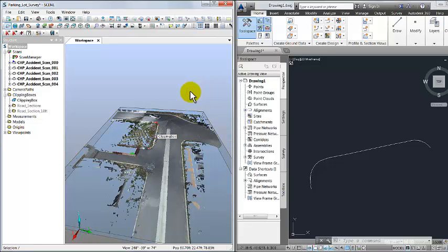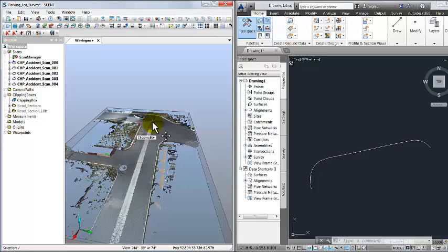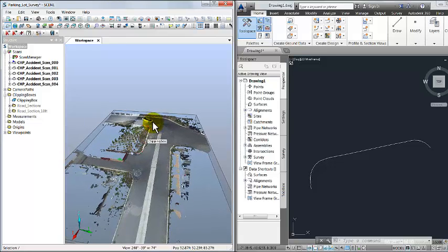Now you can bring the individual FLS files in from the FARO software, which is a very viable solution as well. The one reason I do prefer, even though it takes a little bit more time, the project point cloud is because it's had the overlap reduced, so it's very optimized. It's got no overlap, and the color, as you'll notice here, has been sort of smoothed out, so you have a cleaner looking point cloud.